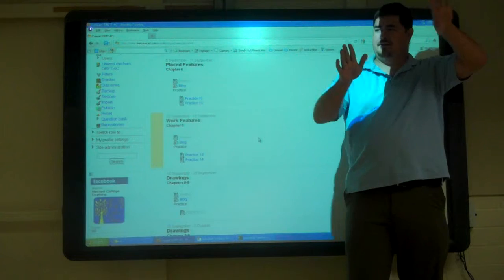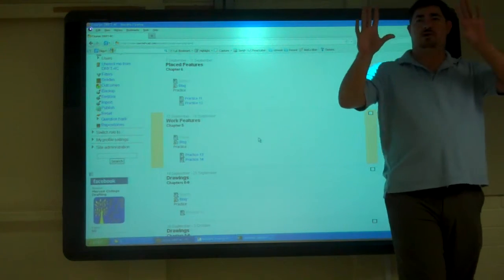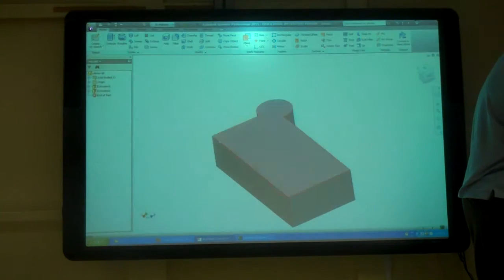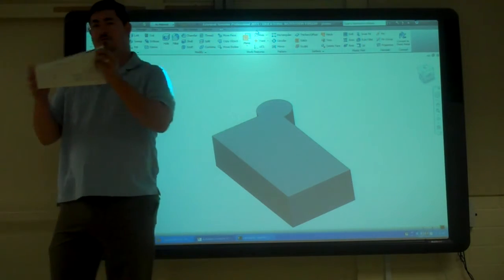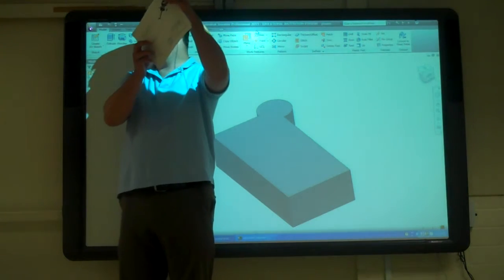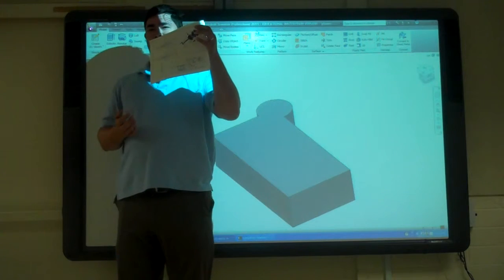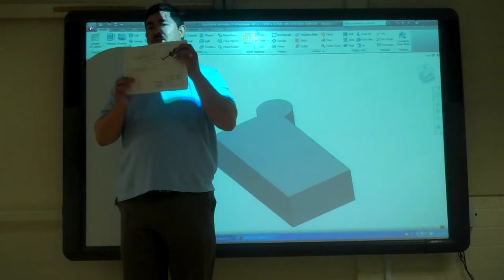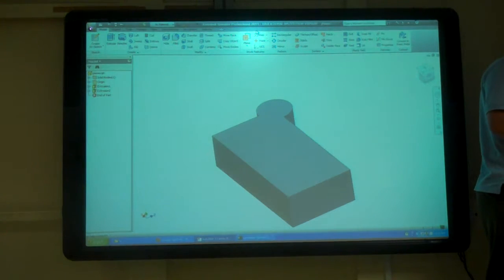But sometimes you want to draw somewhere where you don't already have a plane. So how do you get a plane that's tilted or something like that? And so we use work planes to make those planes. And sometimes to make work planes, we also need to use axes or points. So like on your project, on the portfolio project, kind of the corners are cut off, right? How can you do that? Can you do that just by extruding straight back? You could. That's good. Then you got to do the angles too.